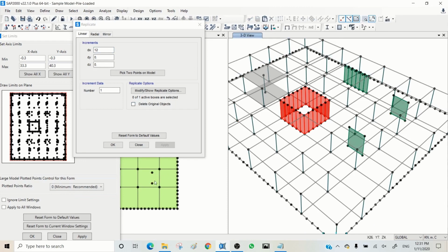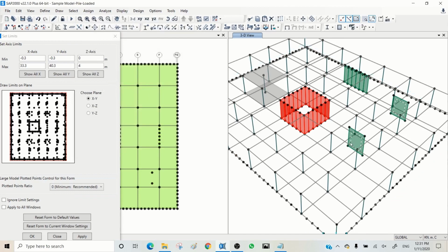I'm doing this intentionally because I want to show you a different way of connecting this wall to the slab. As I said, my suggestion is don't have just 2 points at the end of the wall, because it doesn't give you enough integrity to properly transfer loads to the slab. Better to make it in smaller sizes, just vertical, like what we did for the core wall. So it's roughly about 4 meters. I prefer at least 3 segments for a section. If it's a very small segment, that's fine, keep it as it is. You may have just a 1 meter wall or column, leave it there, that's okay. But if it's a 4 or 3 meter wall, better to subdivide it.